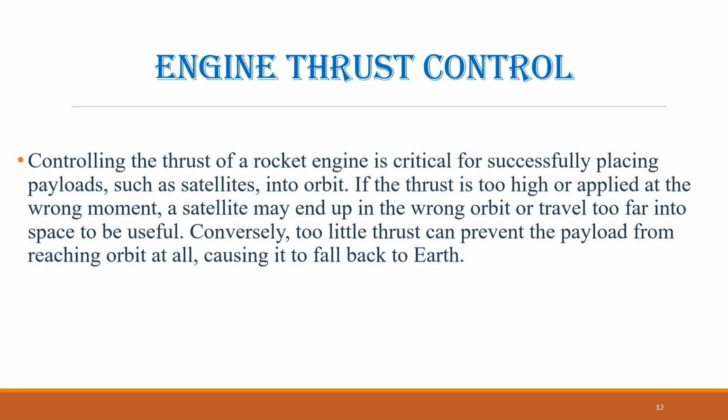Solid propellant rockets, however, are more difficult to control. Once ignition occurs, the propellant burns continuously until it is exhausted. Slowing down or stopping the burn mid-flight is challenging. In some designs, fire extinguishing systems or remote-controlled hatches can release chamber pressure to halt thrust, but these methods are complicated and not always reliable.